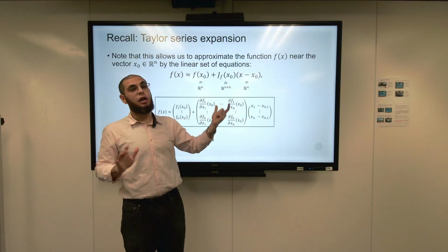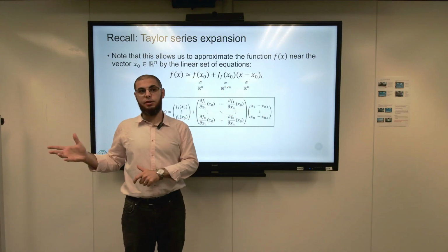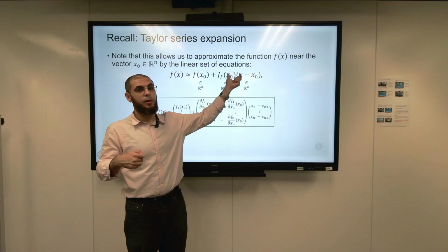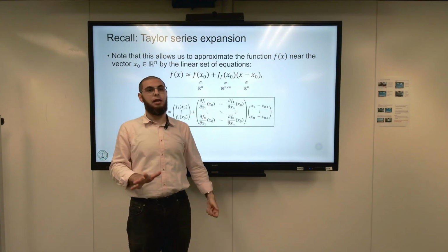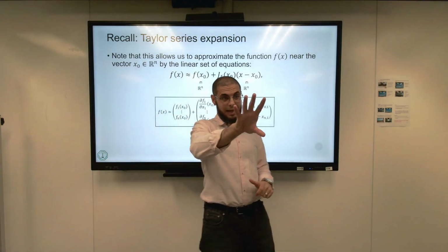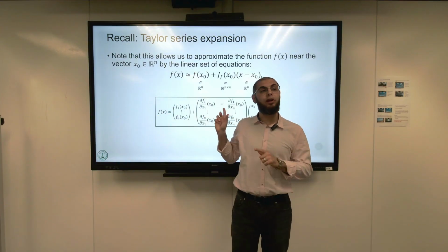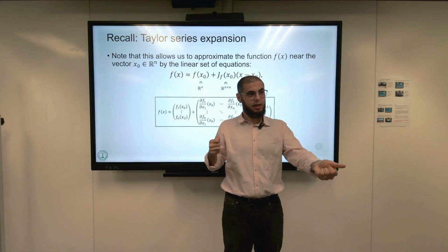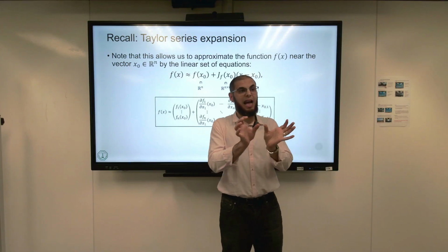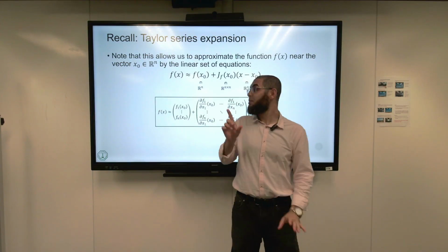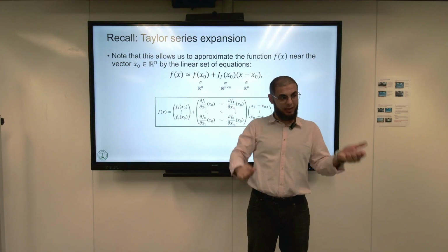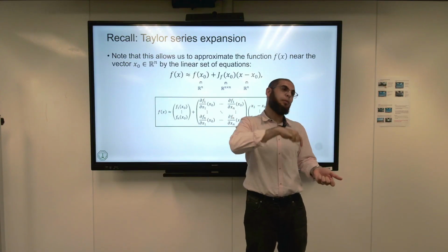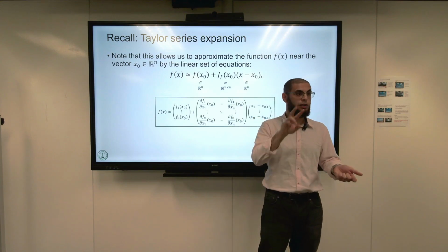It's not just an error because of the noise; there's also an error because of the approximation, approximating the nonlinear part with a linear part. That's exactly why, when implementing the extended Kalman filter equations next lecture, inshallah, you'll see we have a mix of both. We use the nonlinear function whenever we can, and whenever we cannot, we approximate it using the linear stuff. So we're going to be using both.